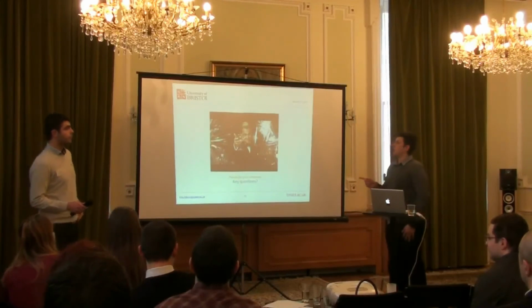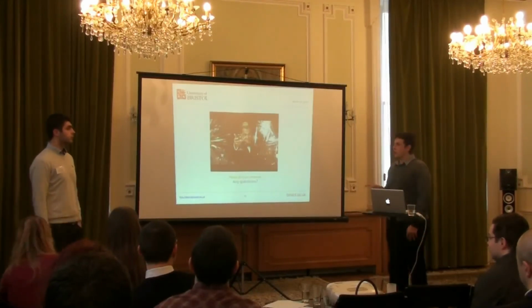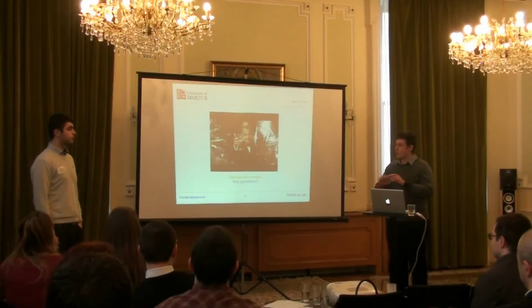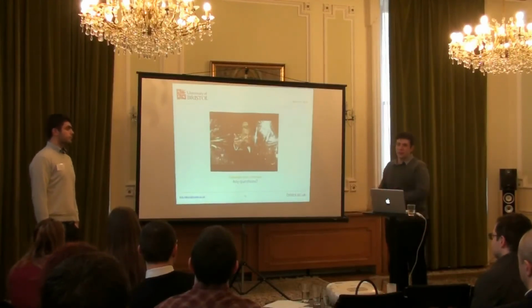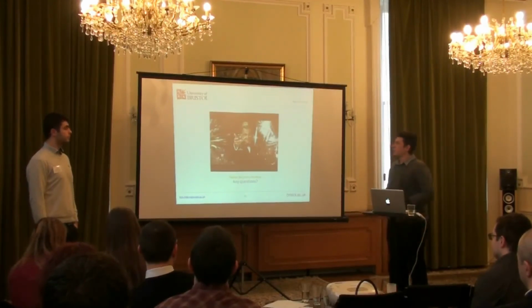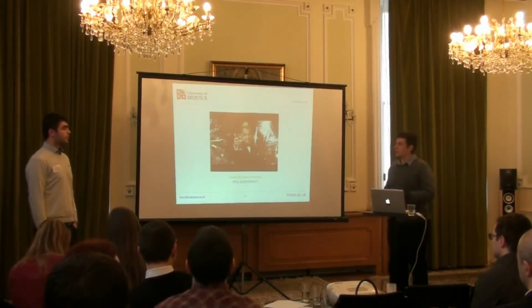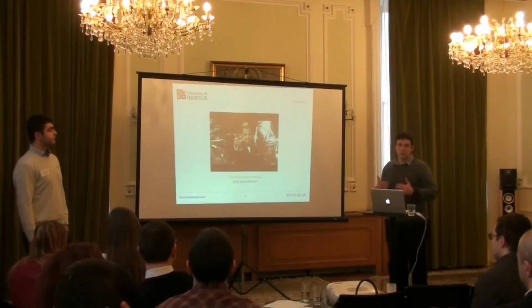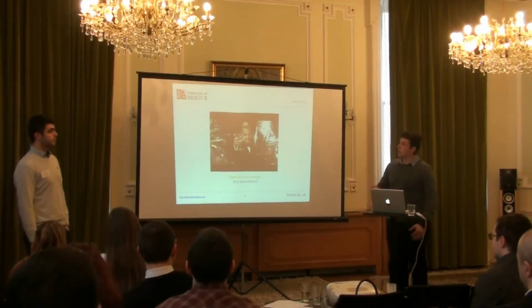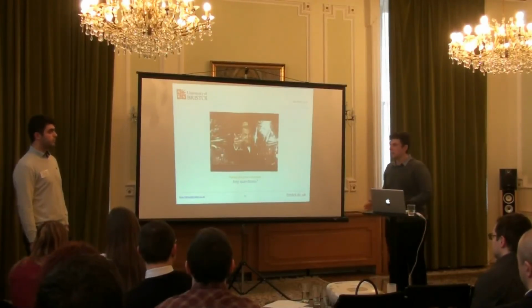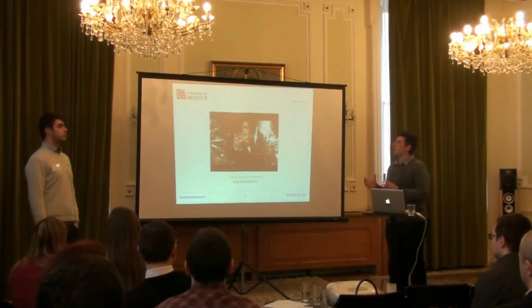That's a good question. Currently, CPU architectures are very complex, so you can't just have one equation simulating everything like you could in the past. It's just too complicated. So using machine learning is the best approach we have at the moment to generate these equations. Other works have used mechanistic information like pipeline depth and the number of execution units, but I've opted not to use that, specifically because I want to make my methodology transferable to other architectures.